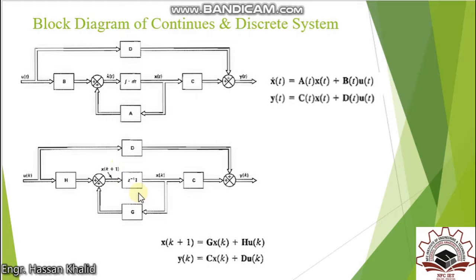If you want to convert the continuous time signal into discrete time values, you need to add a sampler, and to hold those values you use the sampler and hold mechanism, either a zero order hold or a first order hold depending on your requirement, for converting those discrete pulses into a set of continuous staircase values.